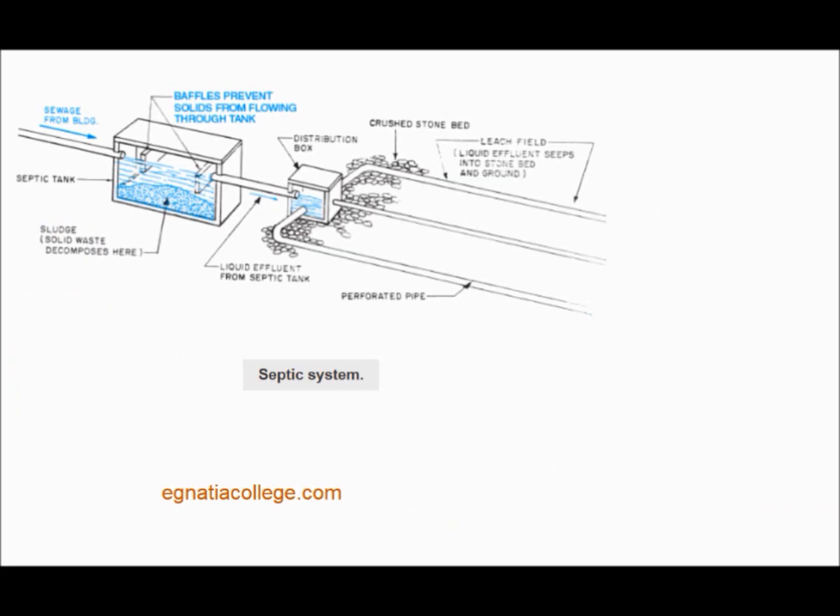Any plumbing that is to be concealed by concrete work must be installed without fixtures or roughed in before the concrete is placed. Because the plumbing contractor installs all plumbing inside the building lines, this phase of construction is discussed later with mechanical systems. The sewer, however, is usually installed after the building is erected to prevent damage due to machinery on the site during construction. The sewer, too, is generally considered a site utility, which is why it is discussed here.